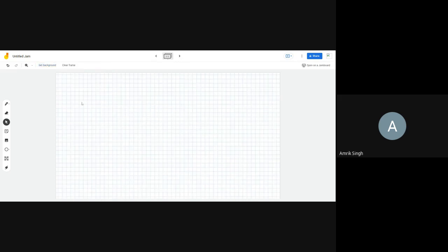So first of all, let us summarize what we have learned in the Euler formula. So Euler's formula, as you know, we determine the critical load, that is PE or PC, is equal to pi square EI divided by LE square, where LE is the effective length.